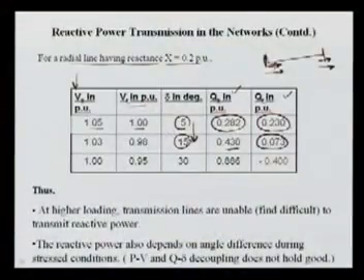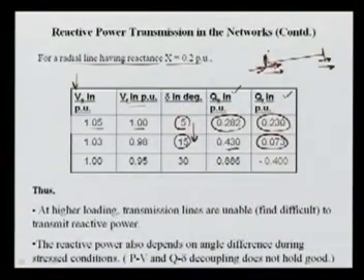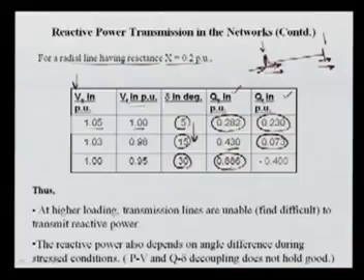In this case the loading is increased from 5 degrees to 15 degrees, which is a very high value. So it requires more reactive power from the source, and the reactive power flowing out is very less, almost 0. Now you can further reduce the voltage, and if this angle is changed more,